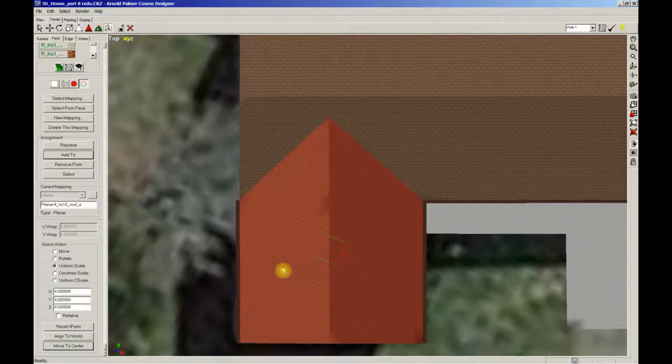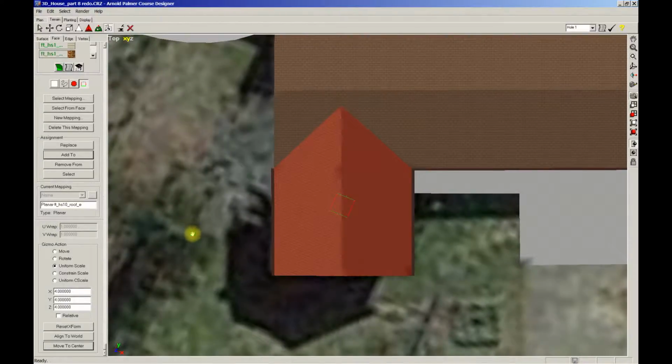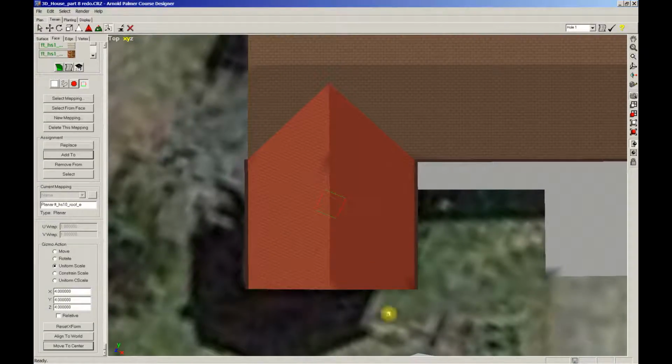And then I want to turn them so they face east. Now this is where I was telling you a while ago. I know north or south is 23 on the z-axis. I know that. So if I set it to 23, it turned them and it faced these things this direction, squared them up. I want to turn them 90 degrees so they face the other way. Well, 90 degrees plus 23 equals 113. So let's put 113 in.